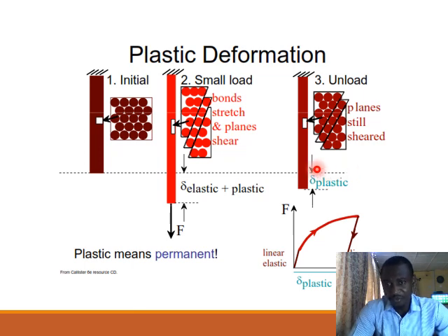If you are using a material for an engineering application, for instance, and the application is subject to the length of the material, a plastic deformation will cause an increase in the length of the material. So if the length will increase, then you don't want the material to deform plastically during operation, so that it will not fail during operation. So this is very important to understand both elastic and plastic deformation of a material.